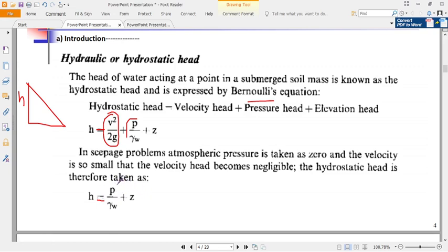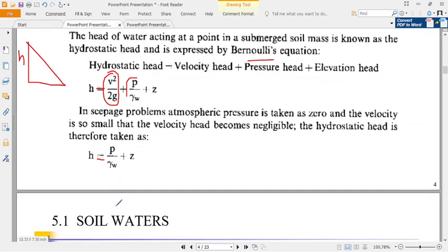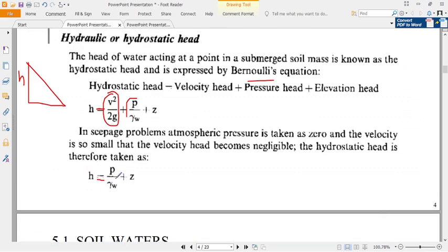We shall fully look at this when we go to what we call seepage analysis, the effective stress, and the effect of the effective stress having a higher hydraulic gradient. So the hydraulic gradient is equal to the head difference over the length.